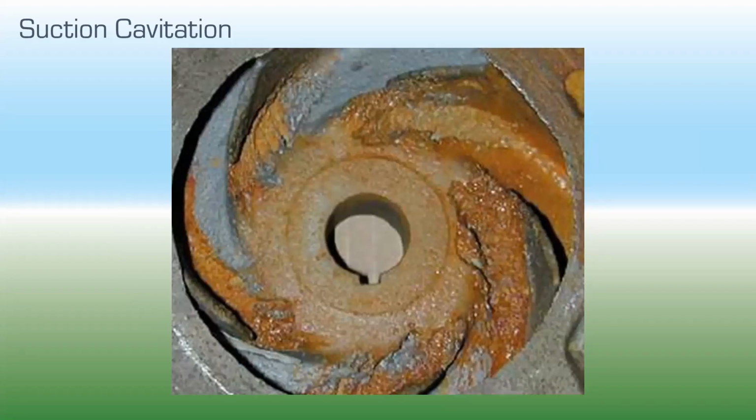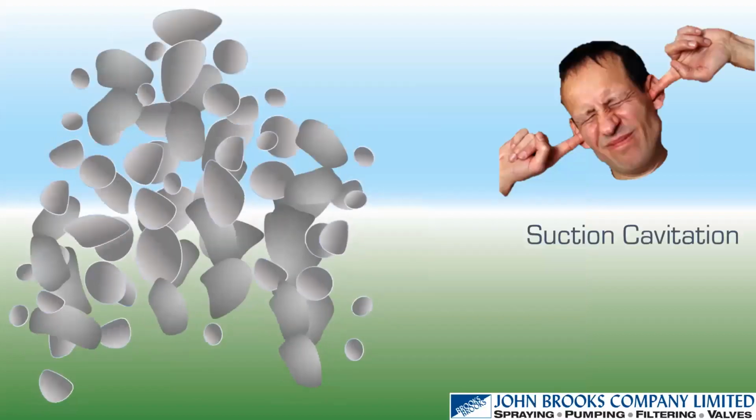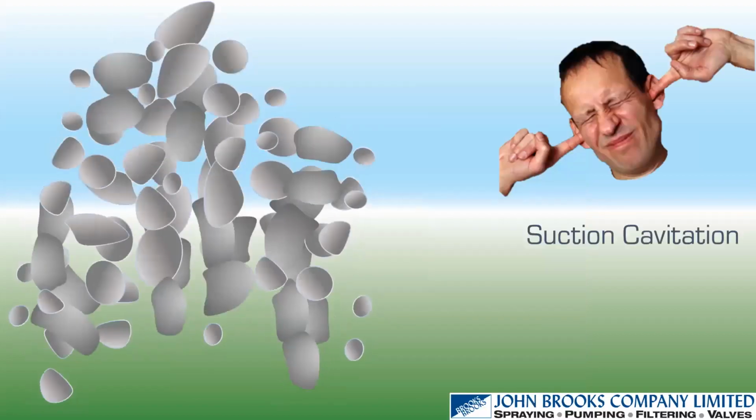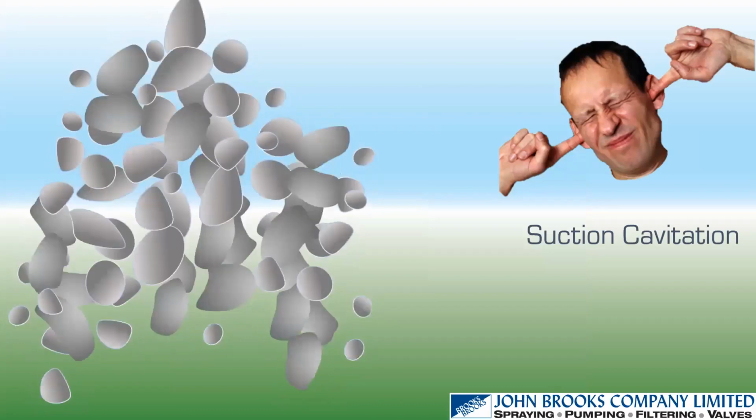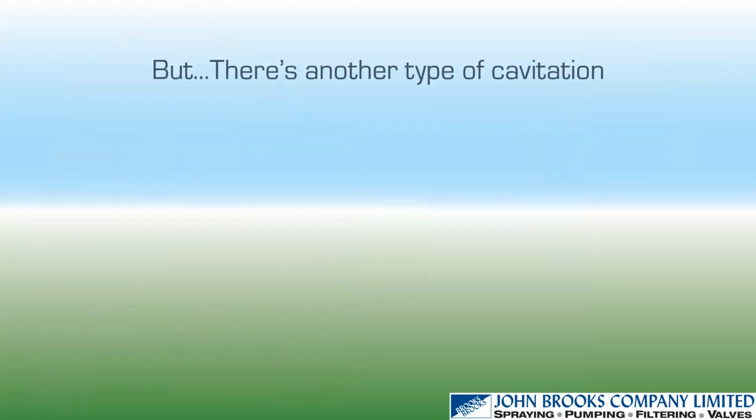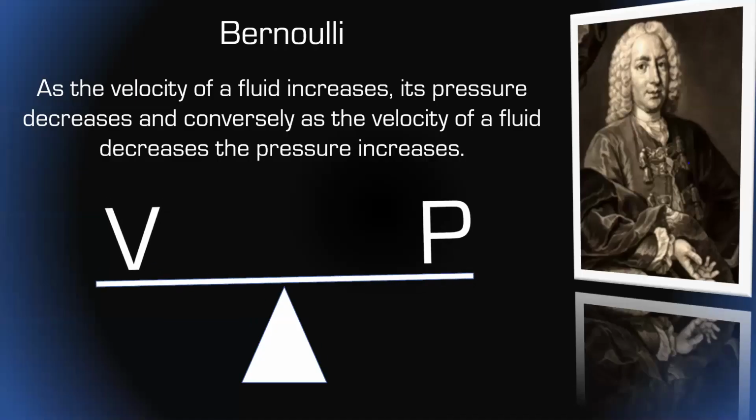If you have not enough NPSH excess, you will vaporize that fluid. And this is very noisy. If I had a pump cavitating right here, you wouldn't hear me. Suction cavitation, very noisy, sounds like marbles or stones. But there's another type of cavitation, there's another two actually, and these ones are a little quicker to explain.